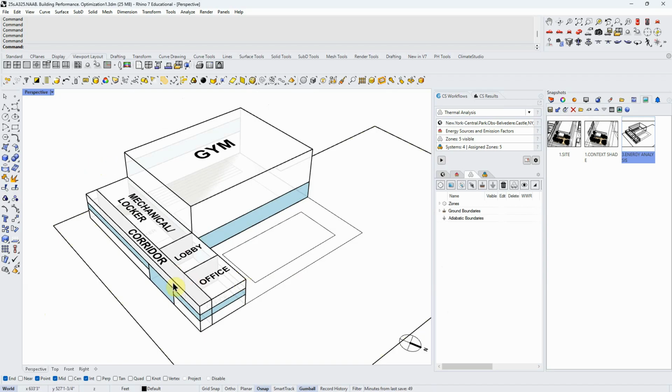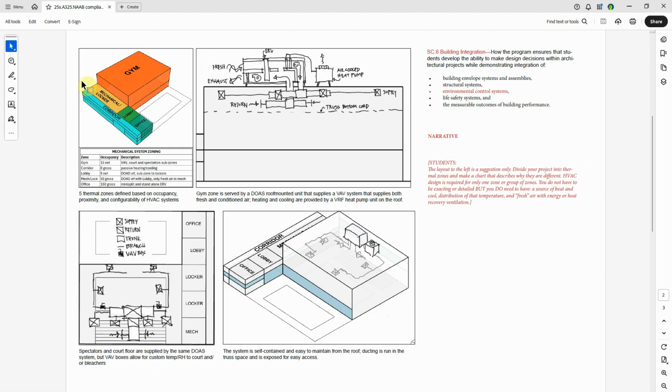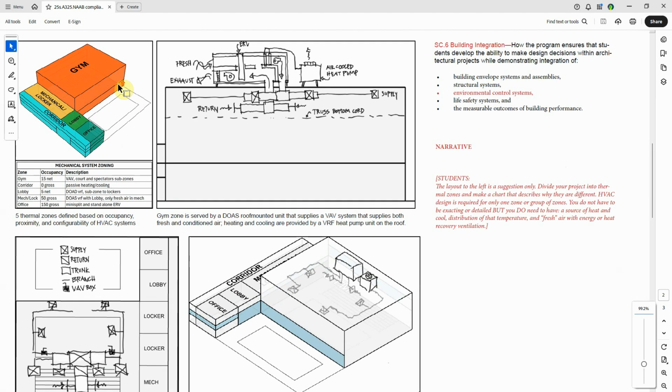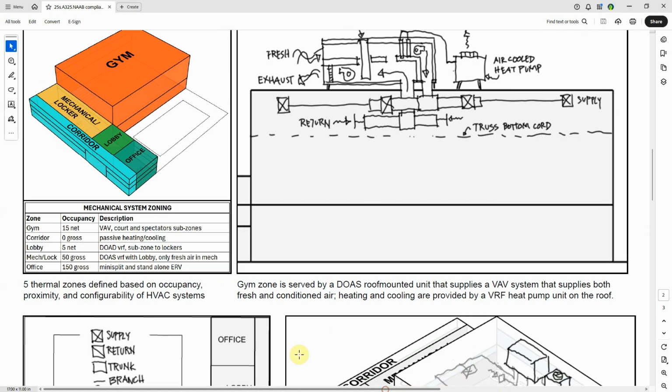we talked about curves. In this case, I added 5 zones. These pages should be designed together. The thing you want to do for HVAC, and this is important because it's much simpler than it could be if you don't listen to this, is define zones for the entire project. So here I've defined these 5 zones, and we want you to create some kind of table that defines what's different about the zones.